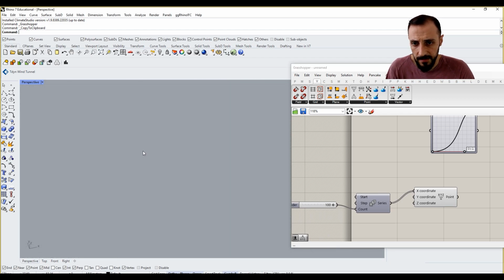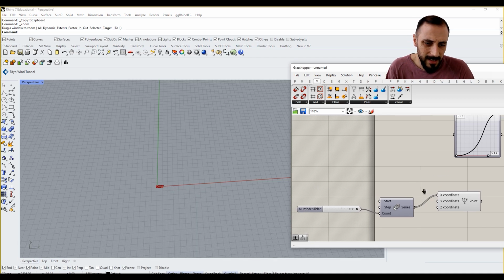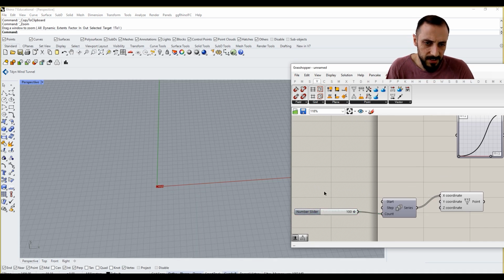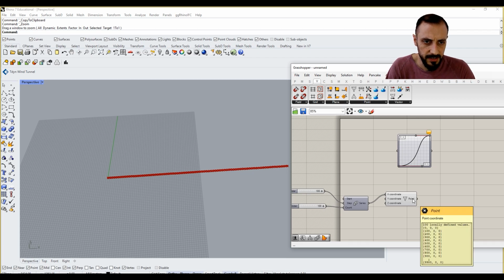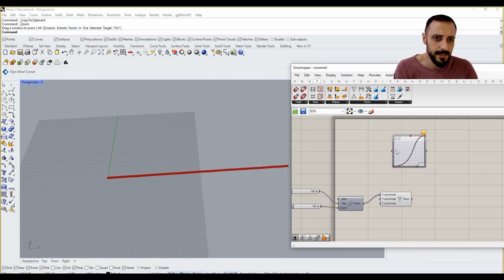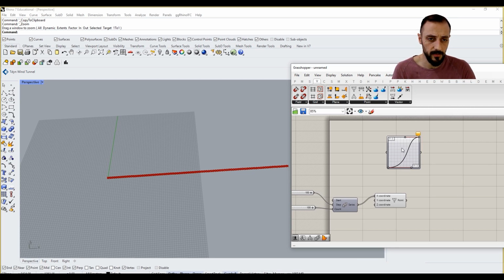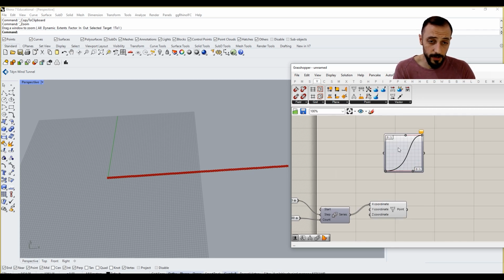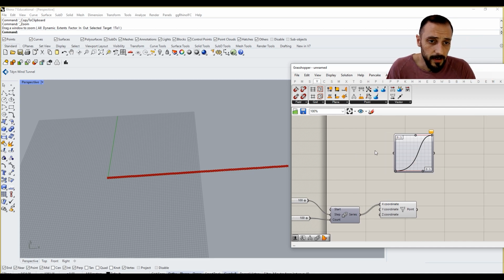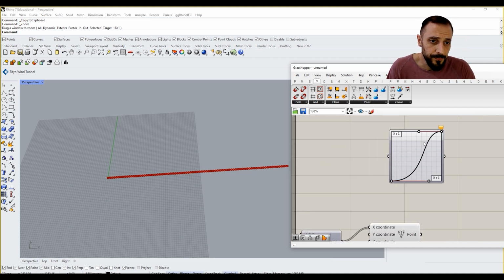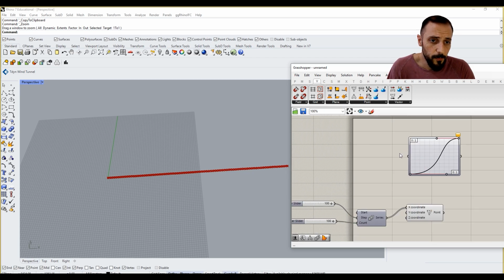You see them here, but a small issue. Okay, zoom in, but they're super small right now because the step number is 1. So why don't we have it as 102? And now we have a bunch of numbers here and they are created as points. As I said at the beginning, what I need is to convert these values into values that I want to change in the z direction. However, first I need to divide this graph into the number of points that I'm having.